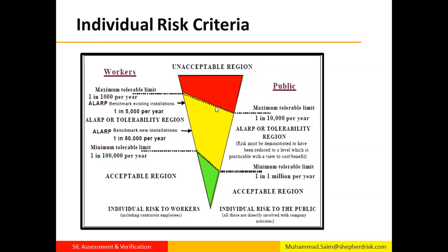All right, so please recommend reading materials. IEC 61511 and 61508 are the governing standards. From the standards point of view, you have to go to those, and they are very detailed, very in-depth. But remember one thing: the IEC does not account for the CPT, the discussion we had. The IEC formulas are simplified formulas. They assume 100% proof test effectiveness.